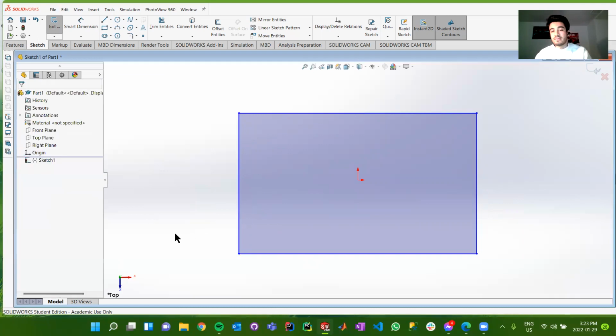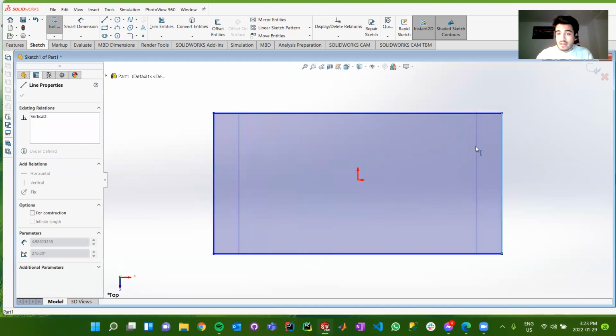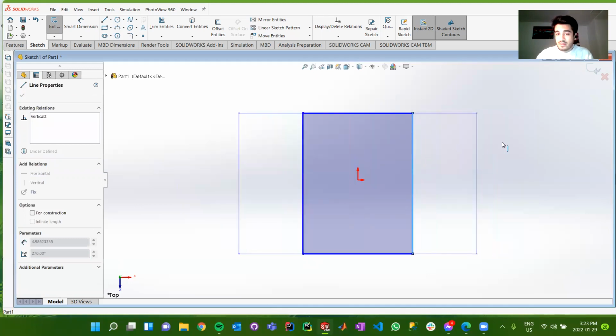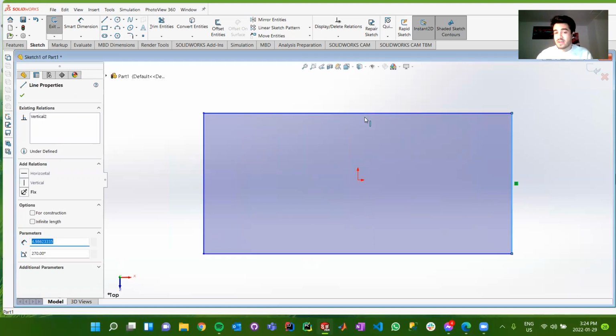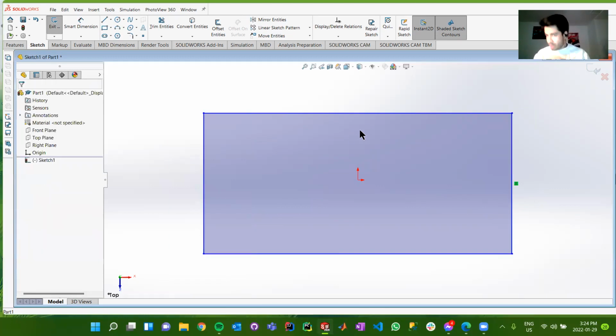And from there, say if I ever want to augment the length of this rectangle, the top width essentially, you'll see if I try to do that with a left click and drag, it will be constrained in a way that the midpoint of this rectangle is always going to be above that coordinate system. So that's pretty good. But you can see we're not done yet.